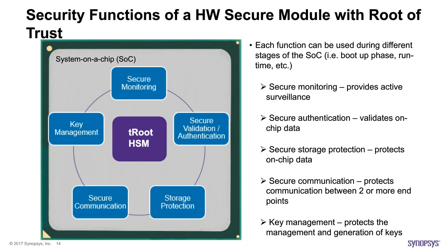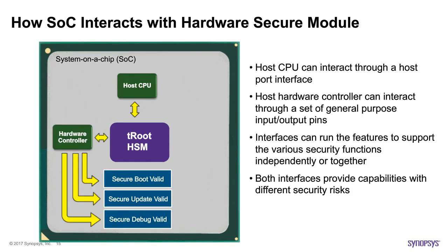So, how can an SoC interact with a hardware secure module? A hardware secure module can be at the heart of the security infrastructure for an SoC. The host can interact with the hardware secure module either through the host CPU and/or through a host controller that can toggle the GPIOs. Both interfaces can be used, but their access provides a different security implication.